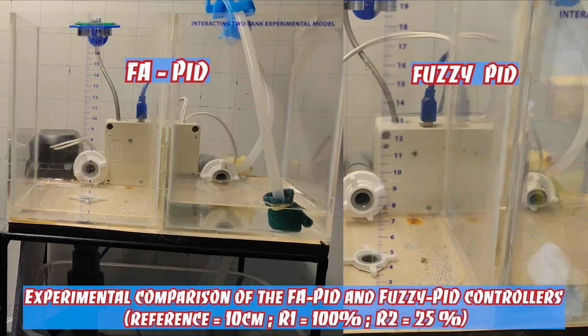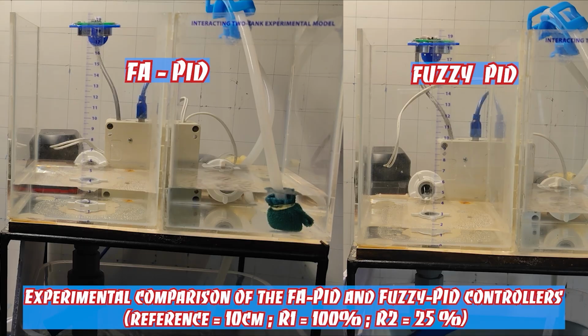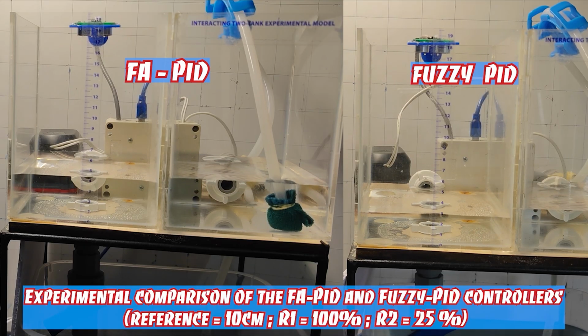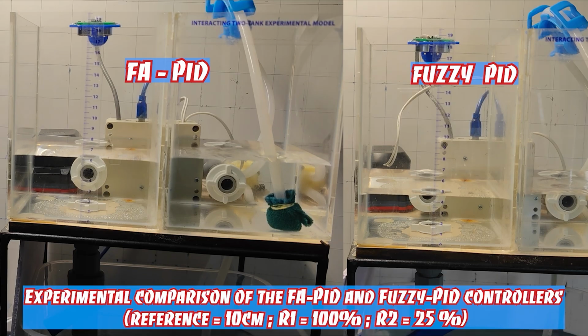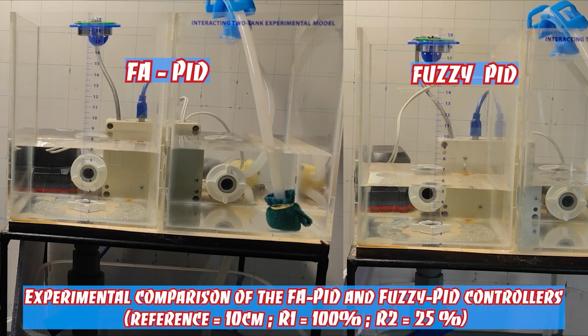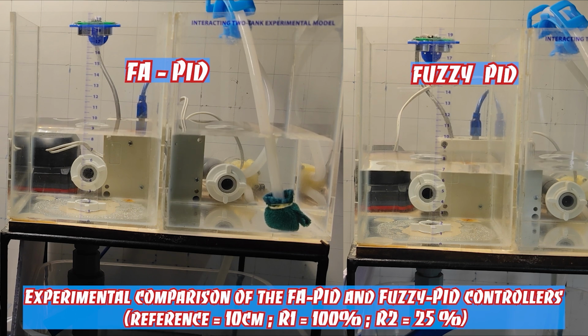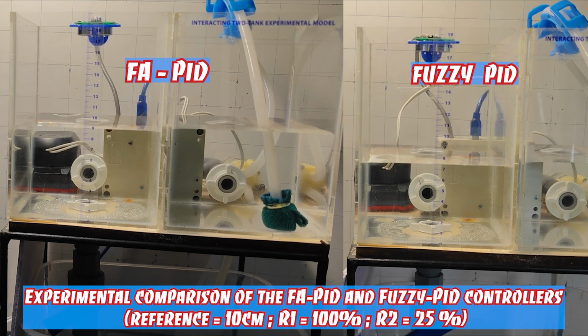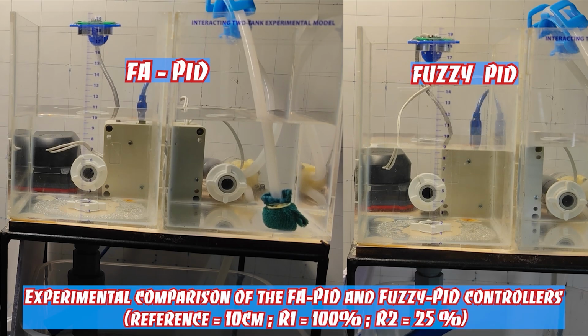In the final experiment, I compared the FA PID controller and the fuzzy PID controller under the same conditions and valve openings. From observation, the response speed of the FA PID controller, shown in the video on the left, is slightly faster than that of the fuzzy PID controller on the right. This demonstrates the advantage of the PID controller optimized by the Firefly algorithm in achieving quicker and more accurate response.